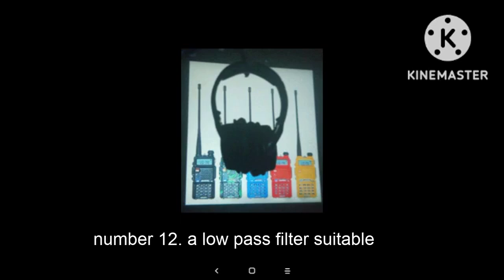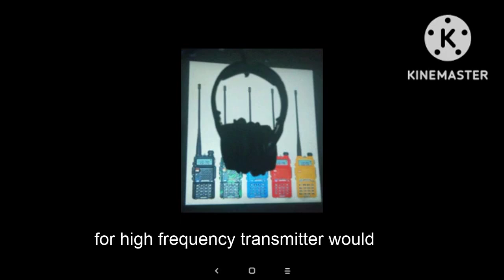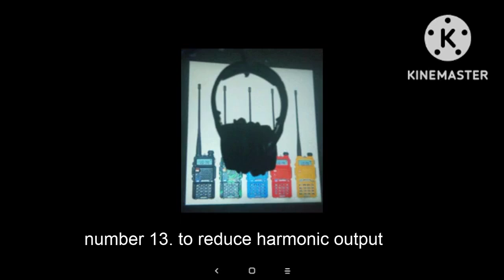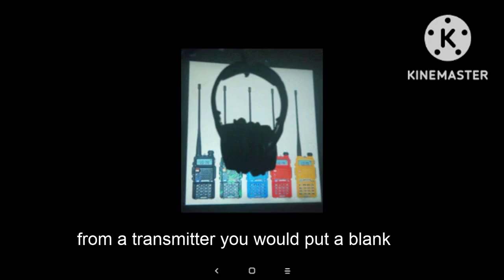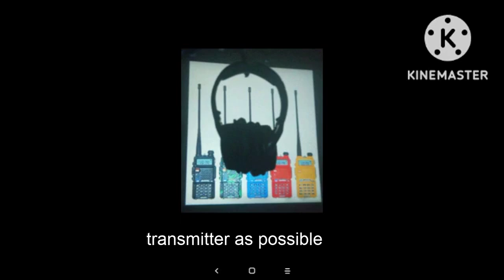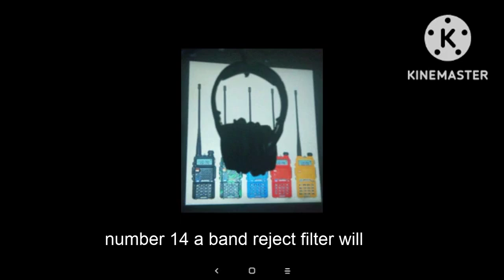Number 12. A low-pass filter, suitable for high-frequency transmitter, would attenuate frequencies above 30 MHz. Number 13. To reduce harmonic output from a transmitter, you would put a blank in the transmission line as close to the transmitter as possible. A low-pass filter. Number 14.